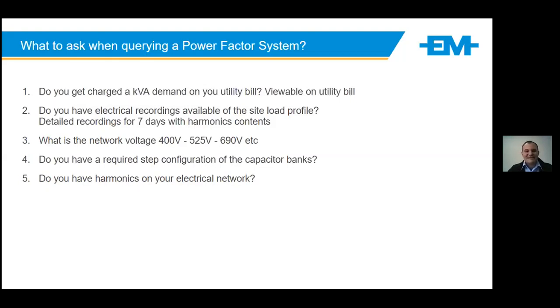Do you have a stick configuration of the capacitor banks? Typically, to be able to do that, you would need recordings. The big question is, do you have harmonics on your electrical network? For the last two, it's going to be very difficult without recordings with harmonic content for the site.